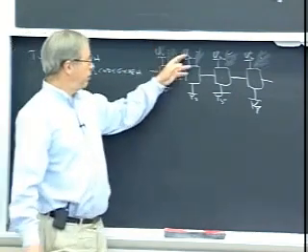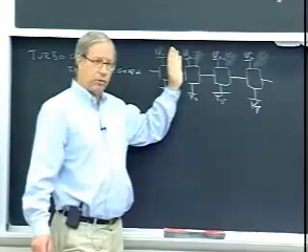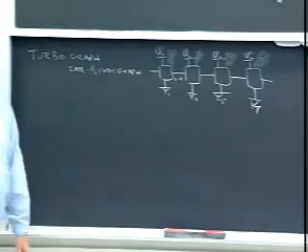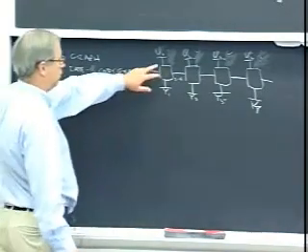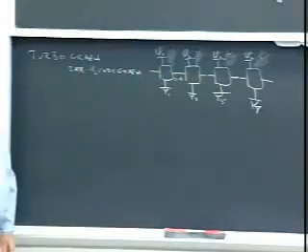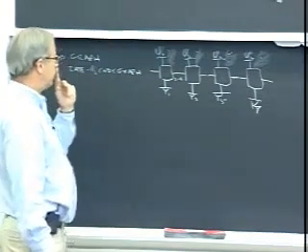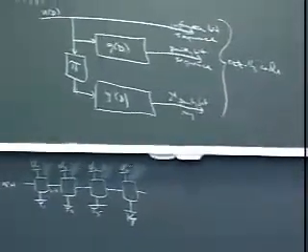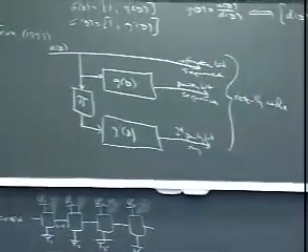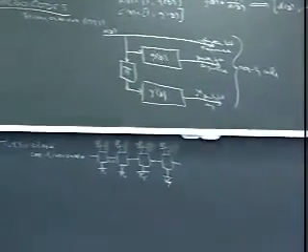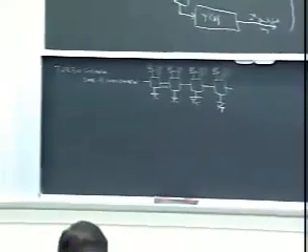Here are these systematic bits, which are both inputs and ultimately outputs onto the channel. These are the parity bits, which are only output onto the channel. All right, and these are the branch constraints for each time. And these are the state spaces for each time. Okay, so I can always draw that way. Now up here, I really have 2 of these codes, possibly identical. And what's the connection between them? The connection between them is that they have the same information bits in some random order, some pseudo-random interleaved order.